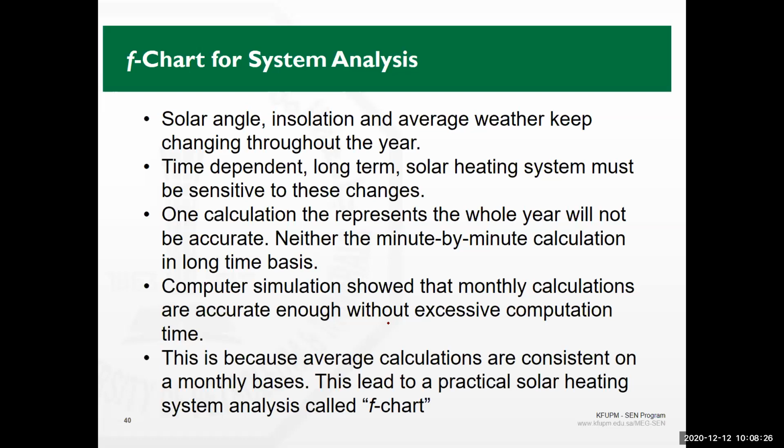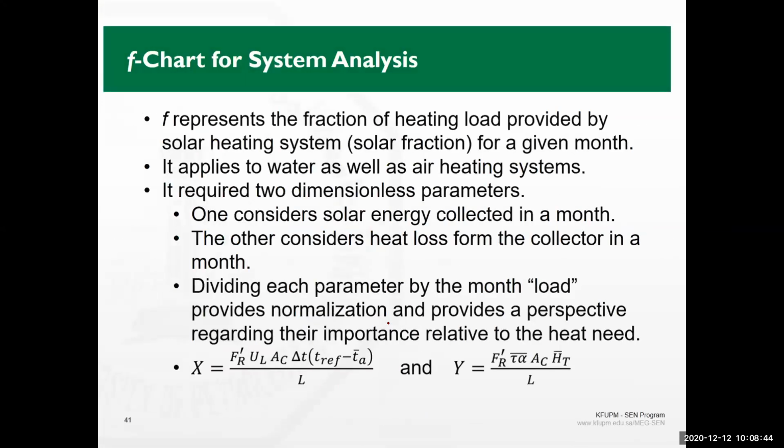There are so many software packages available in the market that do the analysis using the F-chart method. But understanding how it operates, what the F-chart method is all about, is a fundamental thing as you are getting into this kind of analysis. The F represents the fraction of the heating load provided by the solar heating system for a given month. It applies to water as well as air heating systems.